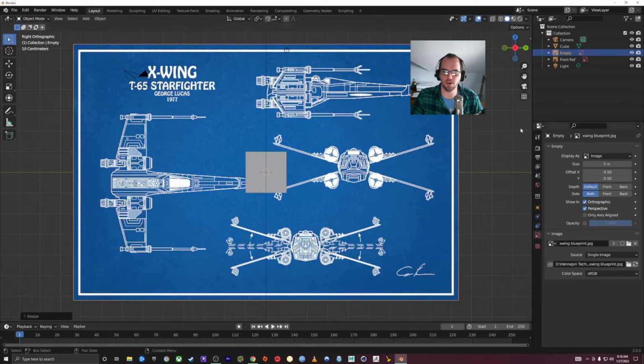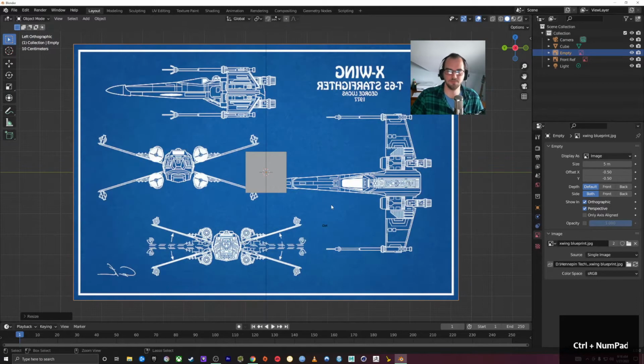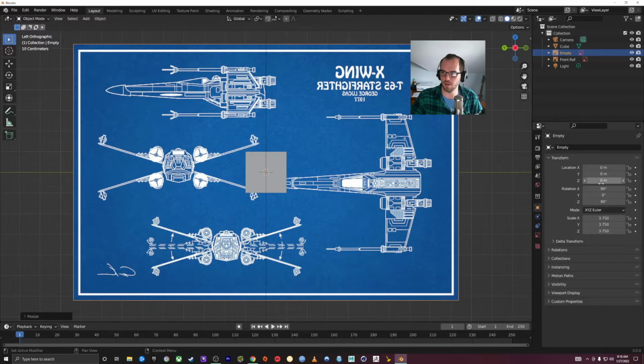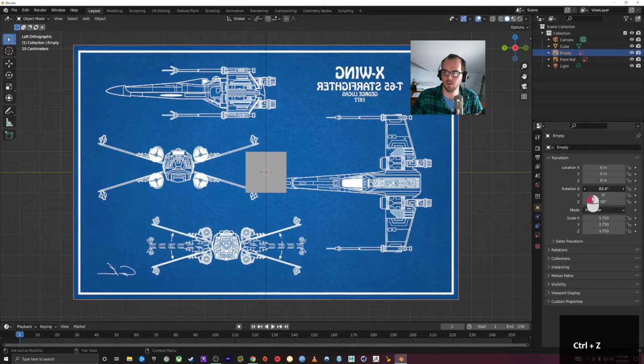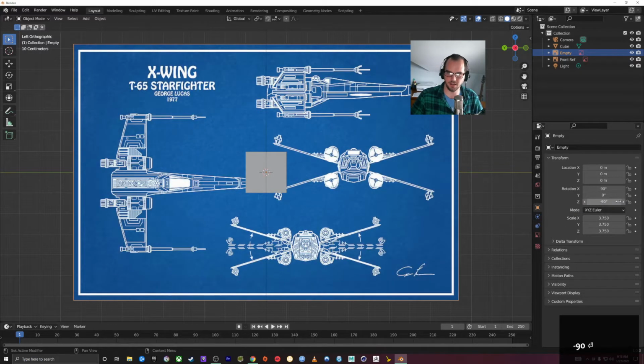So what I'm going to do is there's a couple things you could do. You could actually Control 3 with your mouse in the window, Control 3, and insert it this way so that we're actually looking at the left, and reinsert. But I'm actually just going to transform this. I'm going to rotate the Y. I'm going to rotate the Z to be in -90, like that.